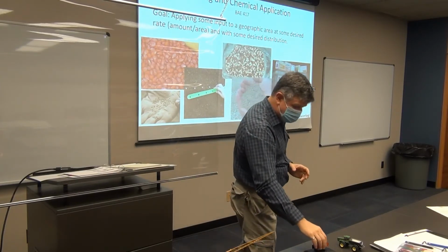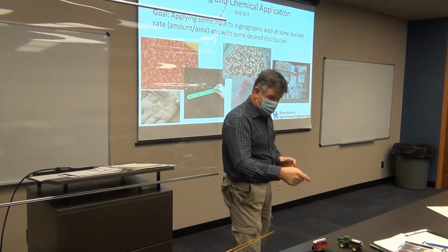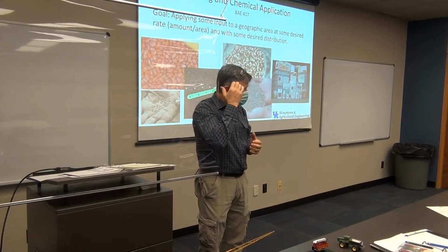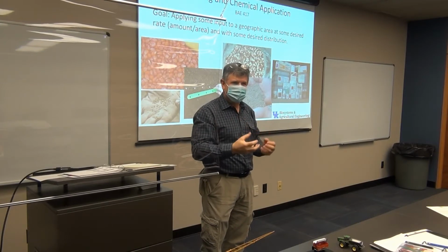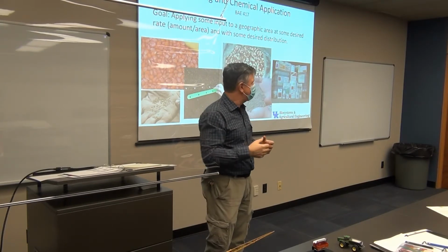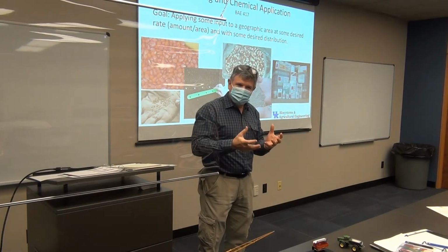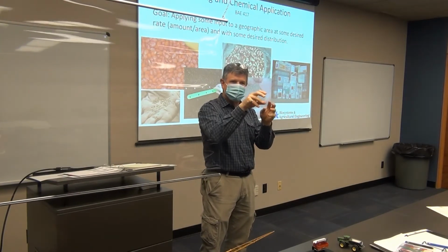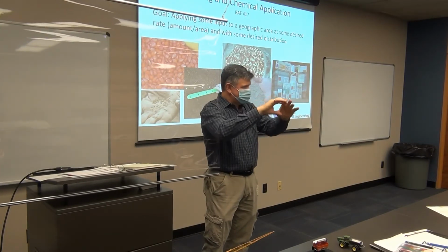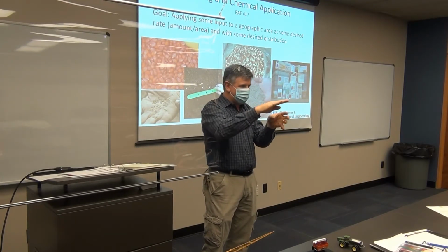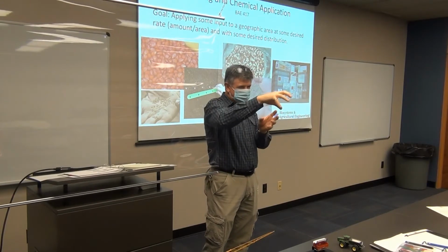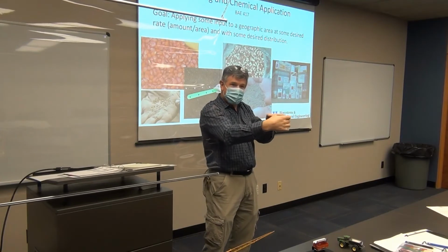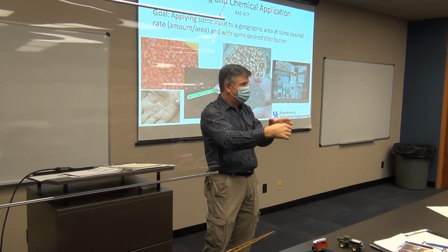So what these guys do, and this is a company out of Germany, I was actually able to tour that company a couple of years ago and talk to their owner, a really fascinating guy, very innovative, looking at some of this spreader technology. But they said, we figured out that a square hole isn't the best. So they've got this teardrop shaped hole that is sort of odd shaped, and as you cover and uncover that hole, it's uncovering it in a weird shape so that as it drops onto the spreader, they're actually controlling how that material falls on that spreader.